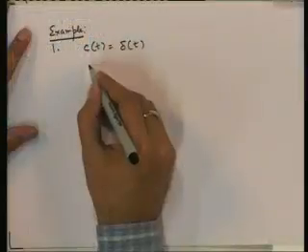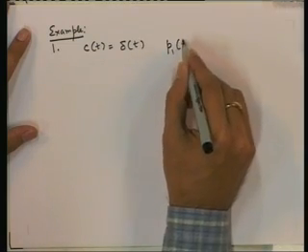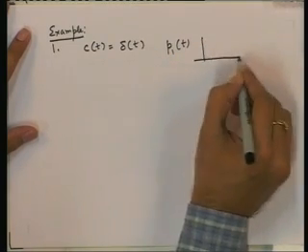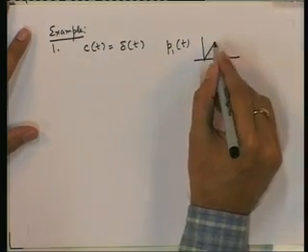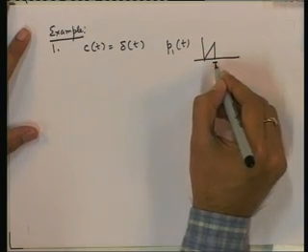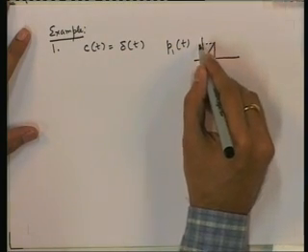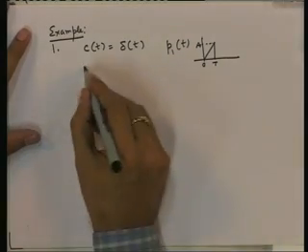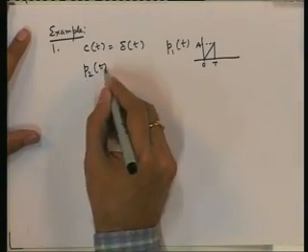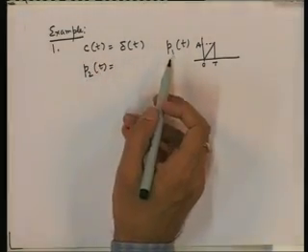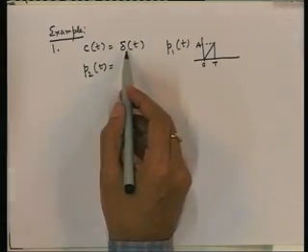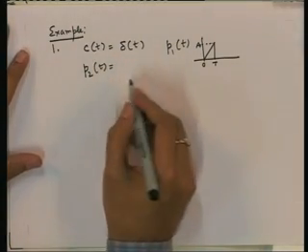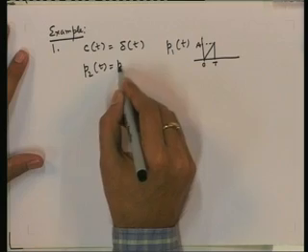Let us say P1(t) is of this shape, some level A. We take this pulse. Then what is P2(t)? If we remember, P2 is P1(t) convolved with c(t). Now, c(t) is delta(t) as assumed. So, this is nothing but P1(t).